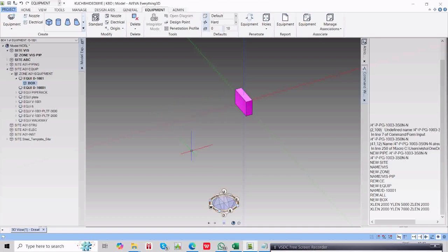First of all, it's a red line, so definitely it's east and west. From 0 it is going toward the left hand side. As you can see here, from 0 the left hand side is west, right? So I have to type a command, by west. How much? Let us say 5000. The value you are writing here is in mm only. So 5000 means 5 meters.